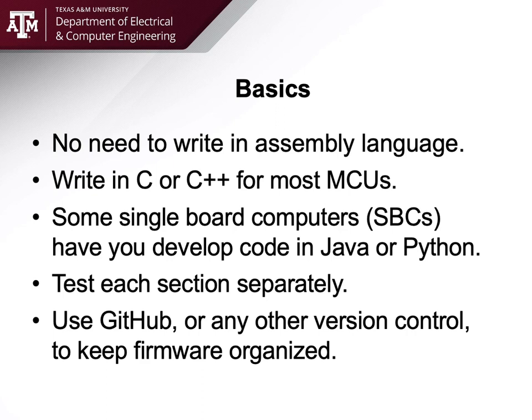25 years ago, this was not the case. 25 years ago, you could actually write better assembly language than a modern compiler. Today, the modern compiler can whip you when it comes to assembly language. They are very efficient because the people who are really good at writing assembly language helped write all of the compilers and made them better and better. And nowadays, they are extremely efficient. Quite frankly, unless you are an extremely seasoned pro, probably at the architecture level of these controllers, you're not going to beat the compiler. And there really is no need to.